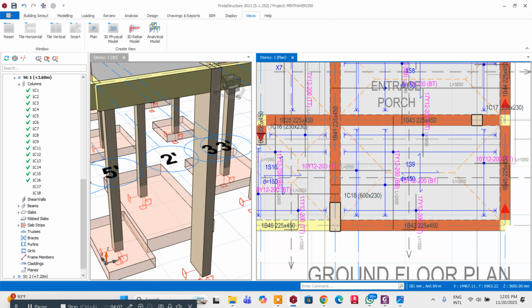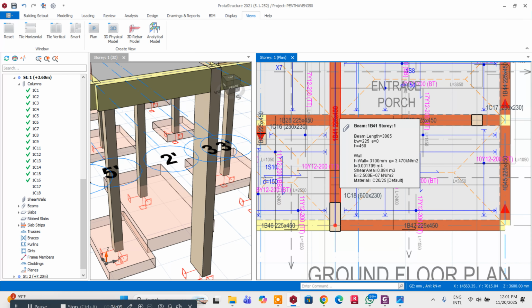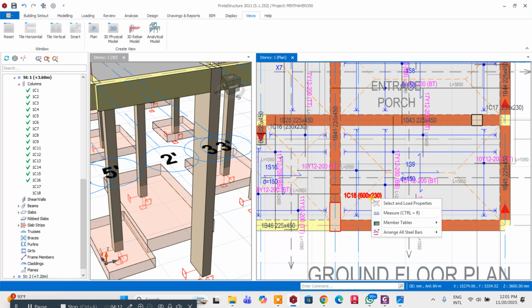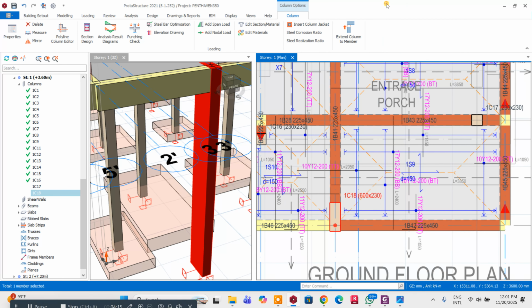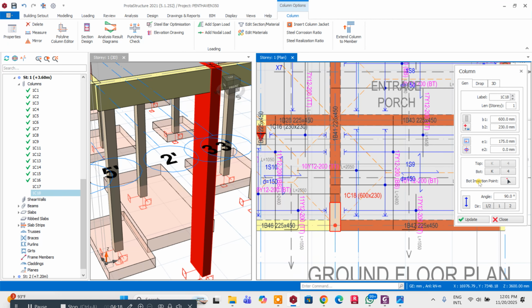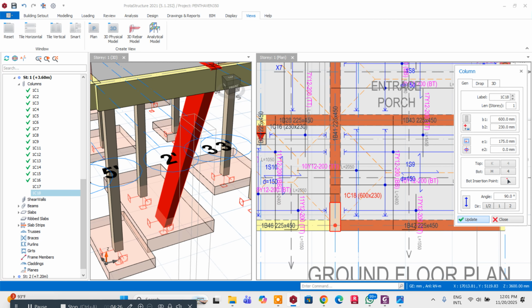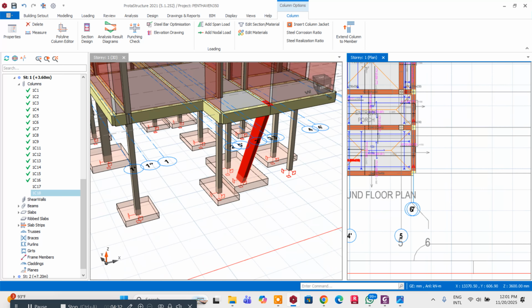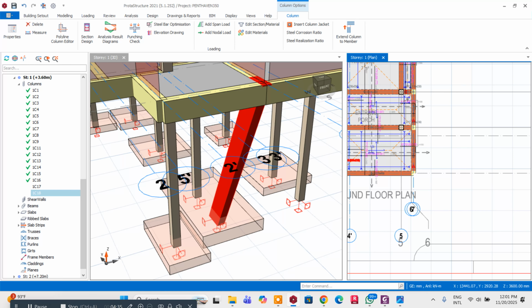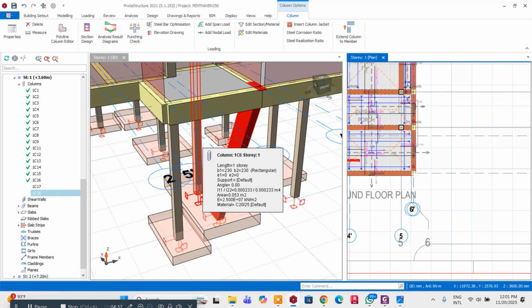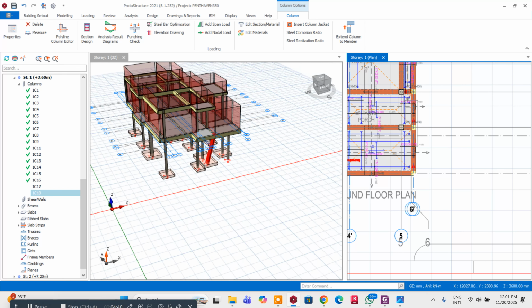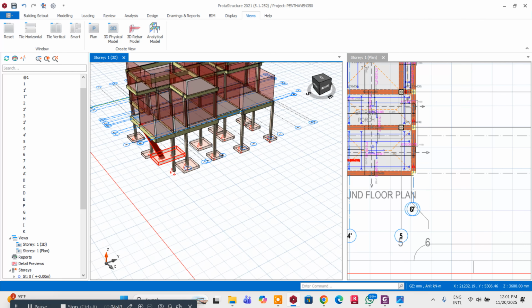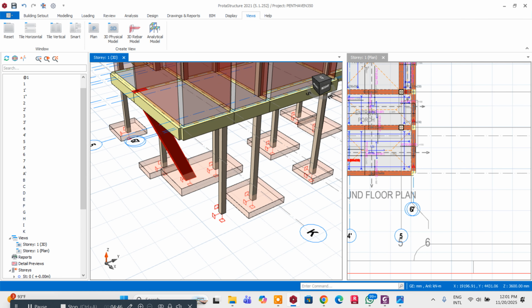And so this is the position at which the column is going to be inclined to this place. So what I will do is click on this, then go to properties and click on both insertion points. I'll click on it, then I'll come here and click. The next thing I'll do is say update and see how your column has moved. Let me reduce this size so that you'll be able to see it. So this is just the logic. At every point where you need your column intersection, you can actually do that. So you can see the way the column is being aligned.